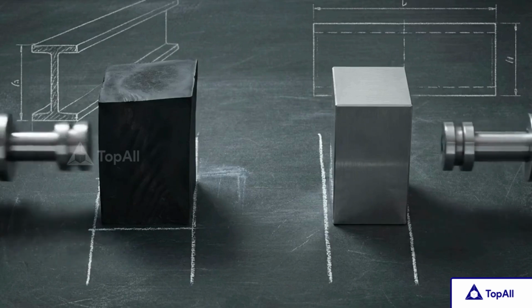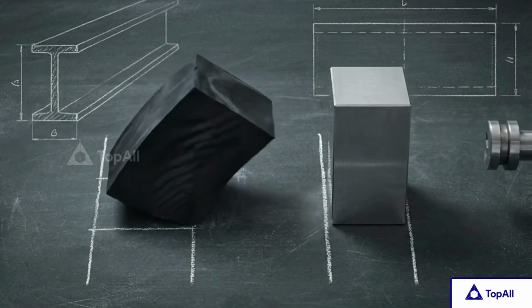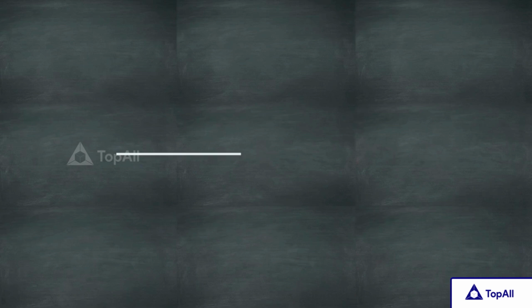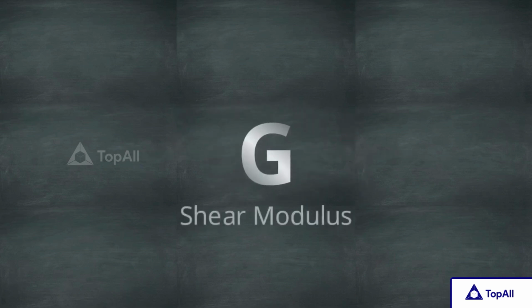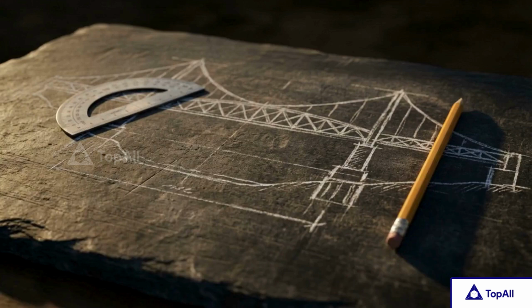To use this in engineering, we need a way to define how much a specific material resists this angular change. That property is the shear modulus, often called the modulus of rigidity, represented by the symbol G. Conceptually, G is the ratio of shearing stress divided by the resulting shearing strain. The shear modulus provides a single constant that defines exactly how much a material will resist sliding under a lateral load. We can now assemble the formal equations used to calculate these forces in structural design.